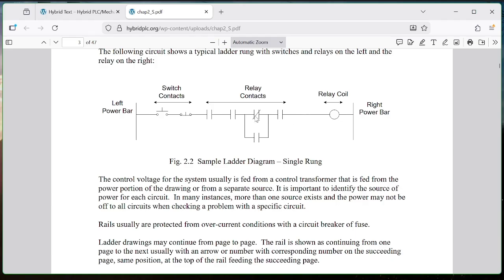Okay, so you go from left to right, usually. Now with electricity, does electricity care? No, it does not care. You can go up, down, left to right, right to left. With electricity, if you bring a circuit back around, you can do that. With a PLC, they had to compromise, and they only allow left or right. No right to left power passing at all on a screen with a PLC.